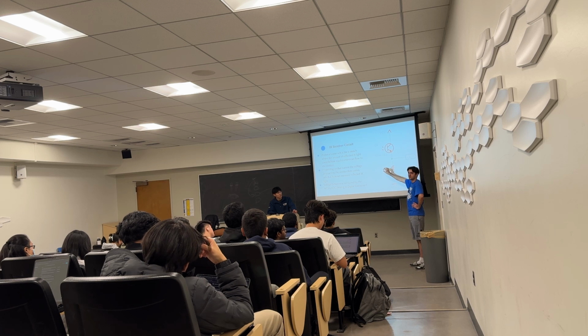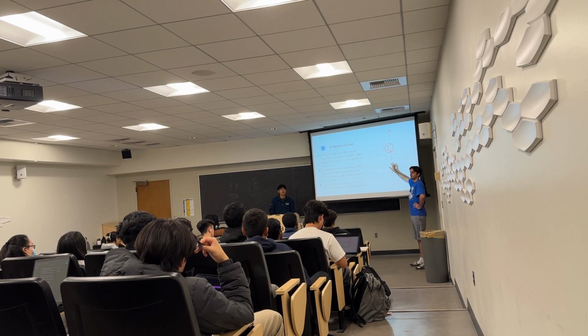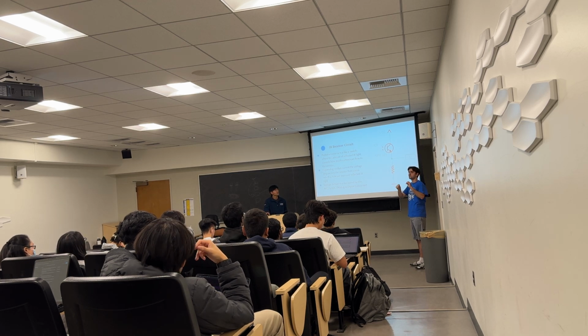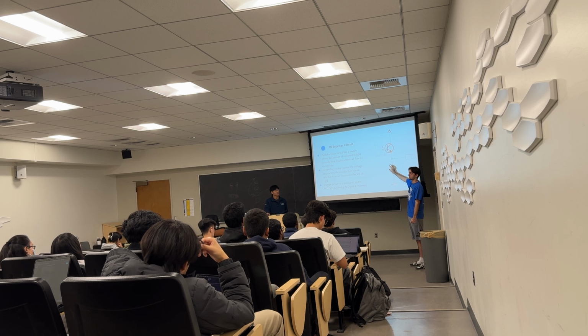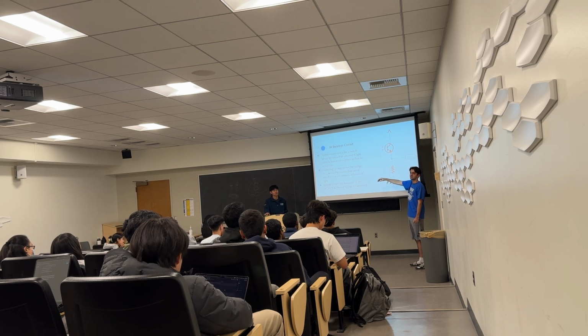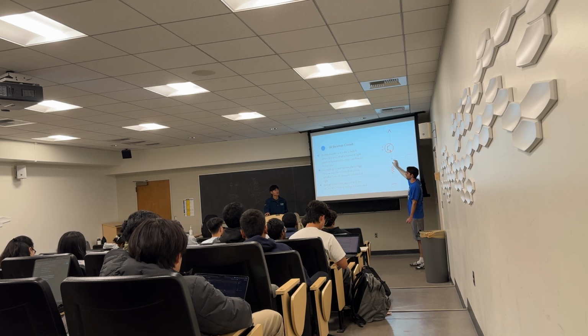Actually, if you've ever used an Arduino with a phototransistor or an IR receiver, you have to choose analog read or digital read. If you were to do digital read on your phototransistor, it's going to do what I just said. It's going to be 1 or 0, which is not helpful at all.